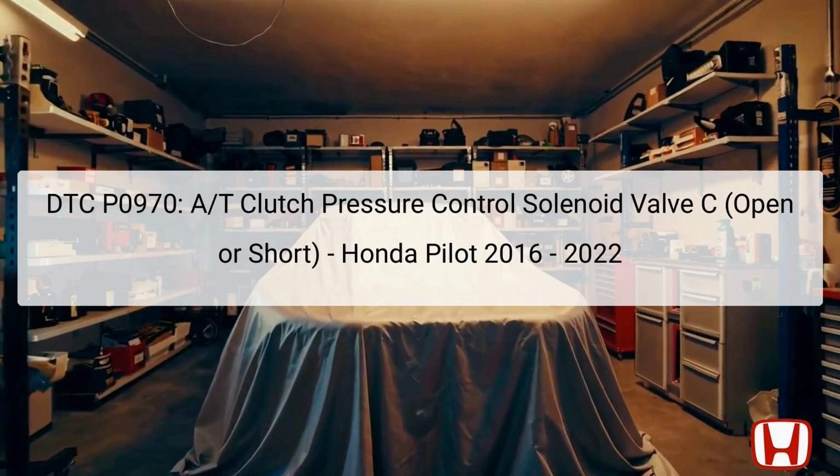The DTC P0970, indicating an issue with the AT clutch pressure control solenoid valve C, has significant implications for the Honda Pilot model years 2016 through 2022. This error occurs when there is an open or short circuit in the electrical system associated with this solenoid valve.